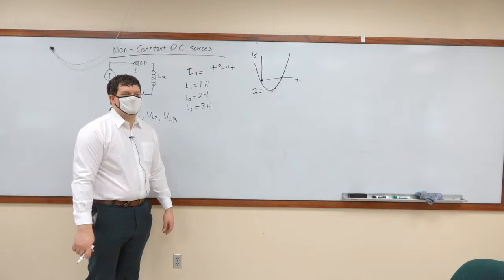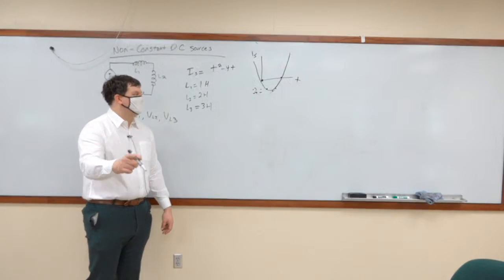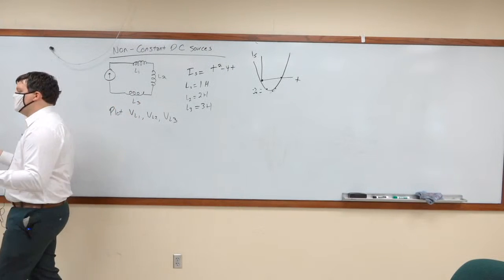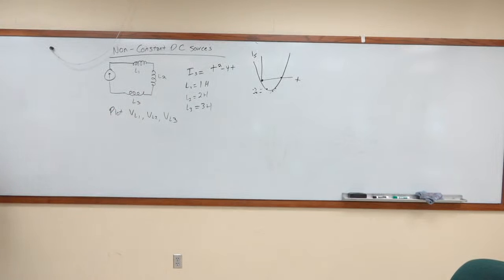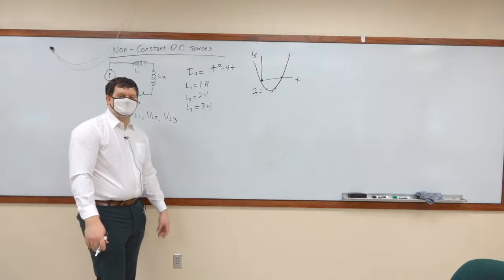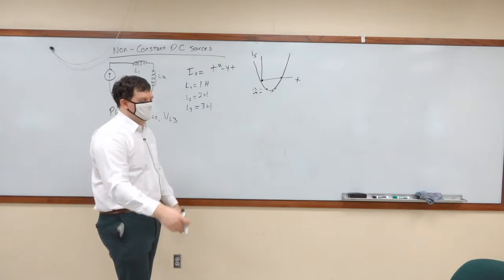Yeah, you're getting ahead of me though. But yes, you are right. What's true about components in series is that components in series all have the same current. Have to, according to KCL. If they're in series, they have the same current. Okay, and because they're in series, then yes, your equation is right. You just took one step ahead of me.